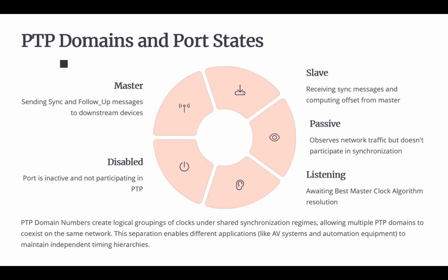Several PTP systems can run side by side on the same cable, each staying in its own lane using the domain numbers. So they code their domain by the domain numbers. This separation allows the different systems to maintain their own independent timing.